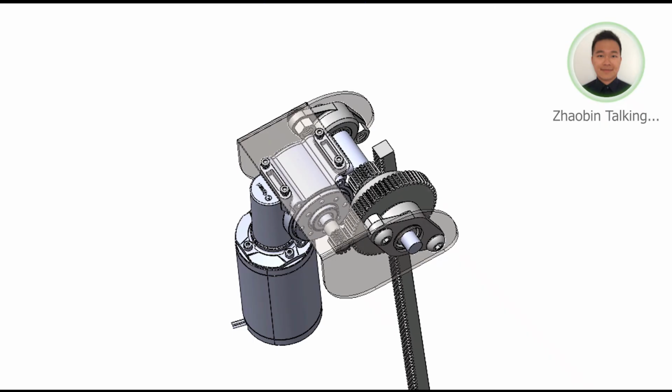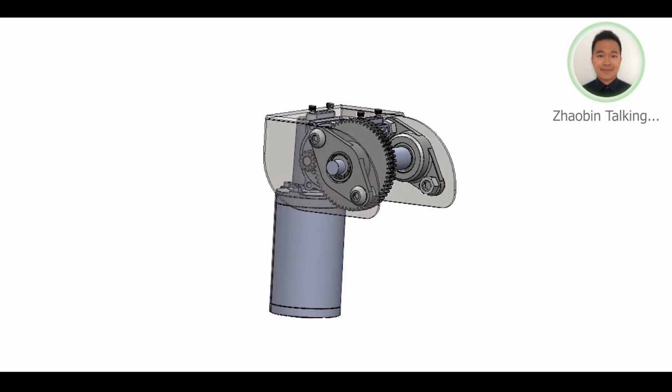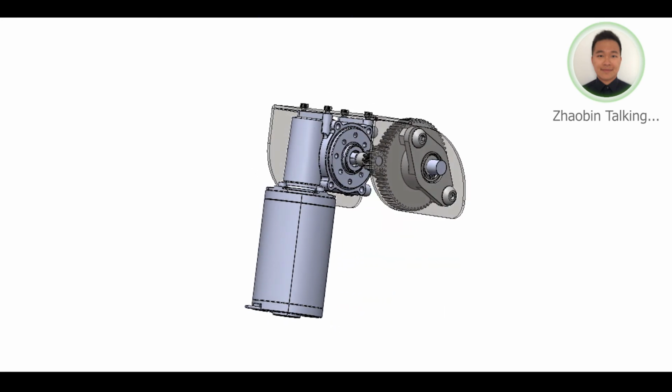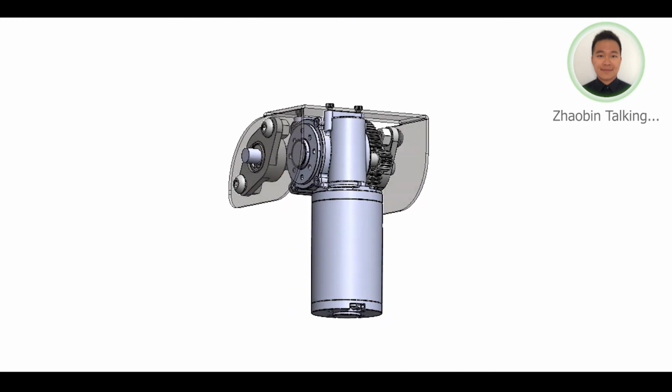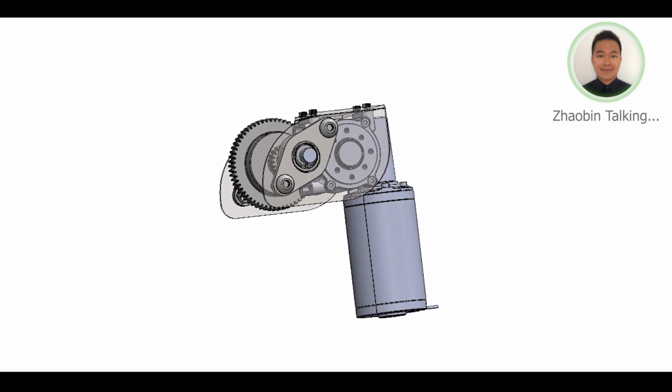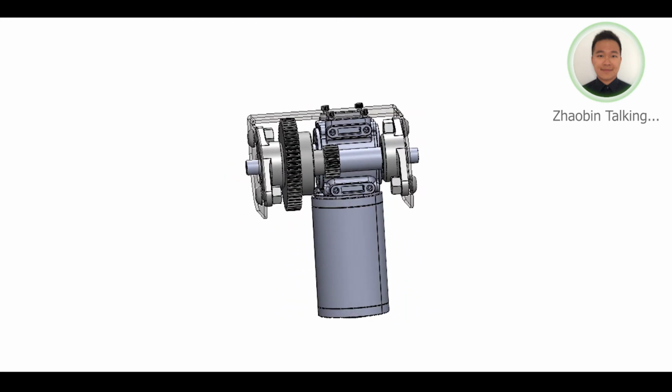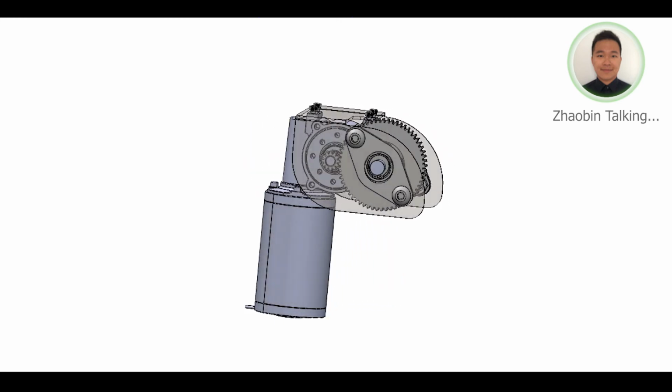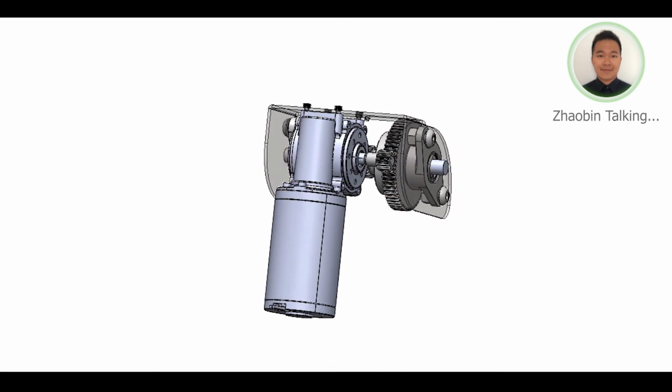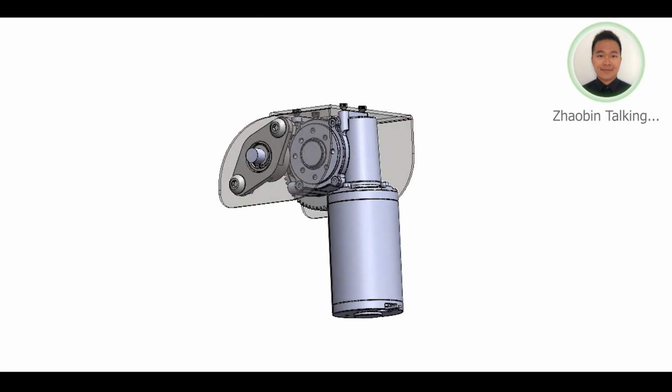To keep it simple, we designed the cabinet with a rack and pinion mechanism, and it would be powered by an AC motor. The AC motor would be compatible with the outlets we usually have in our room, so that is convenient. And the motor is mounted on the top of the cabinet, so the pinion will be able to run from the top of the rack all the way to the bottom. In our case, the pinion actually stays in place while the rack goes up and down with the TV.